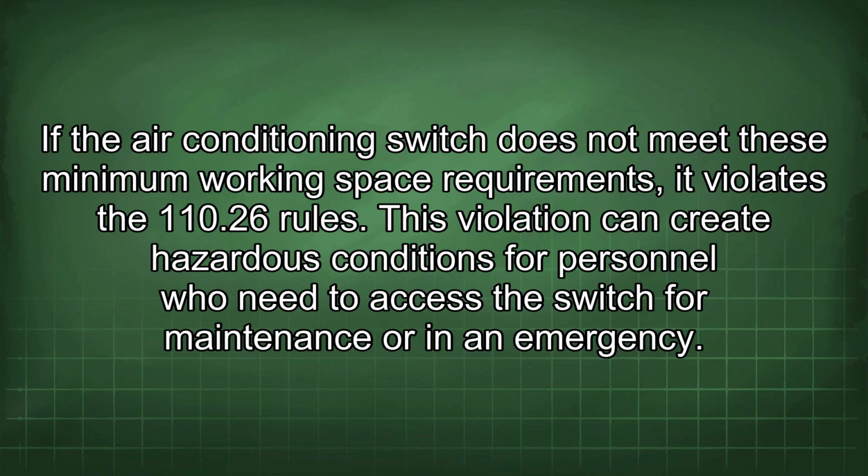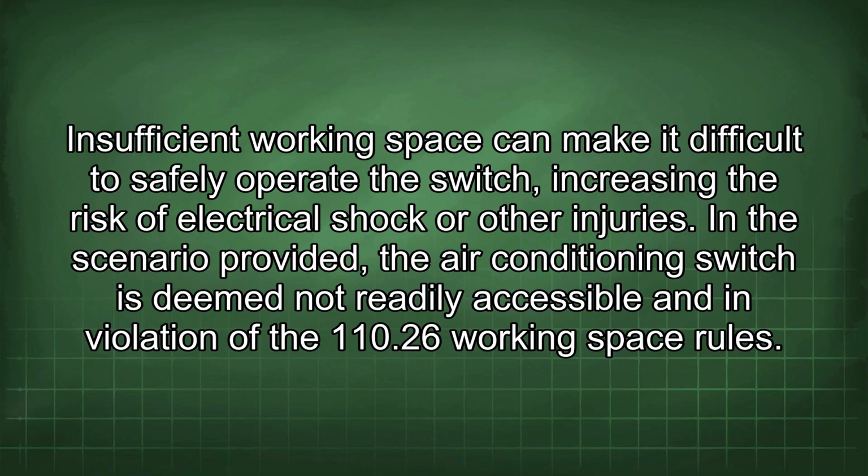If the air conditioning switch does not meet these minimum working space requirements, it violates the 110.26 rules. This violation can create hazardous conditions for personnel who need to access the switch for maintenance or in an emergency. Insufficient working space can make it difficult to safely operate the switch, increasing the risk of electrical shock or other